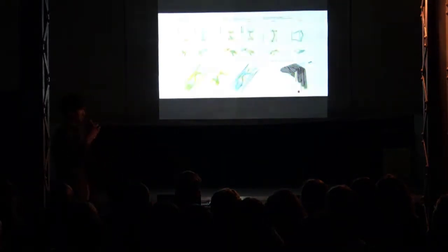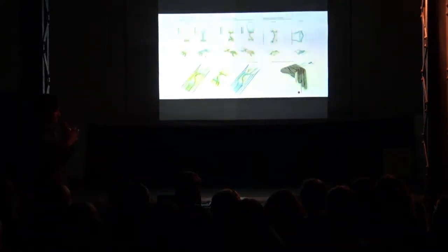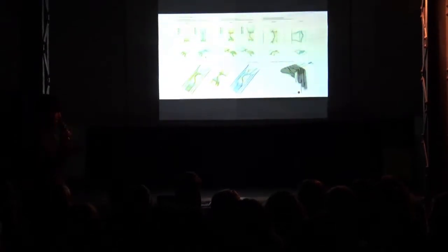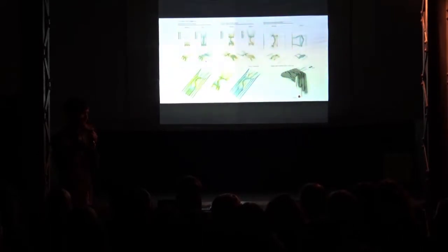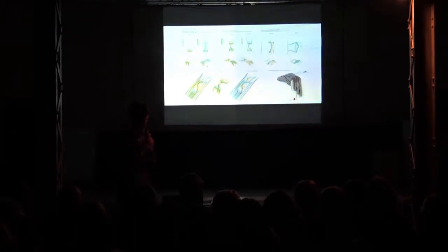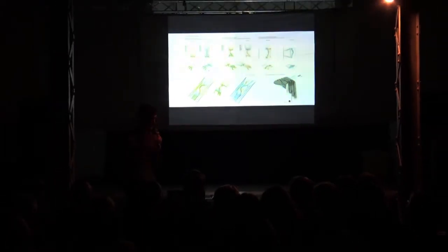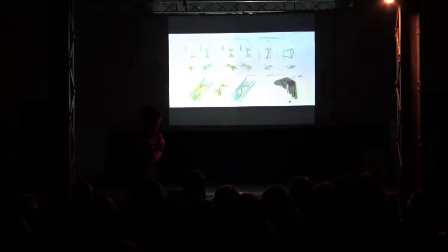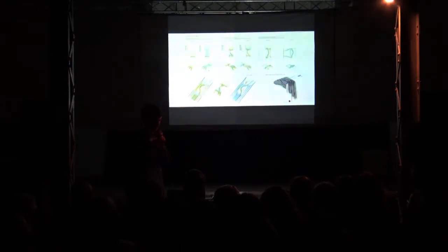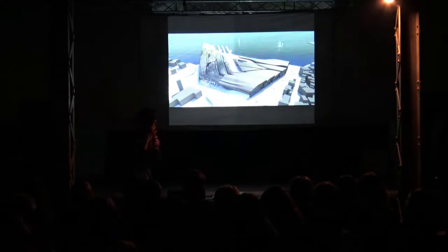And then once we found these relationships that we liked, we ran it through computational fluid dynamics in order to test how the wind behaves once it hits these figures. And according to the information, we then went back and remodified the geometry so that it can prevent these pockets where the wind would increase, or completely stop the vortex coming behind the geometry.